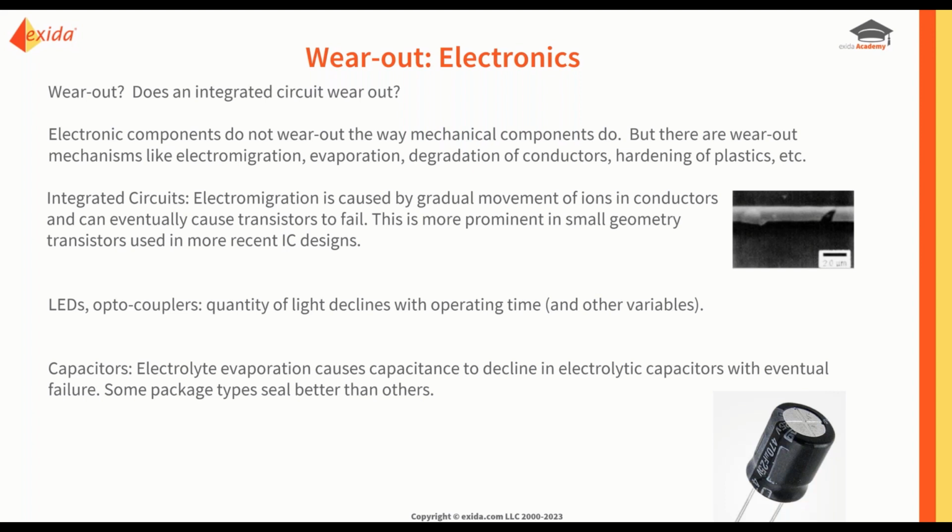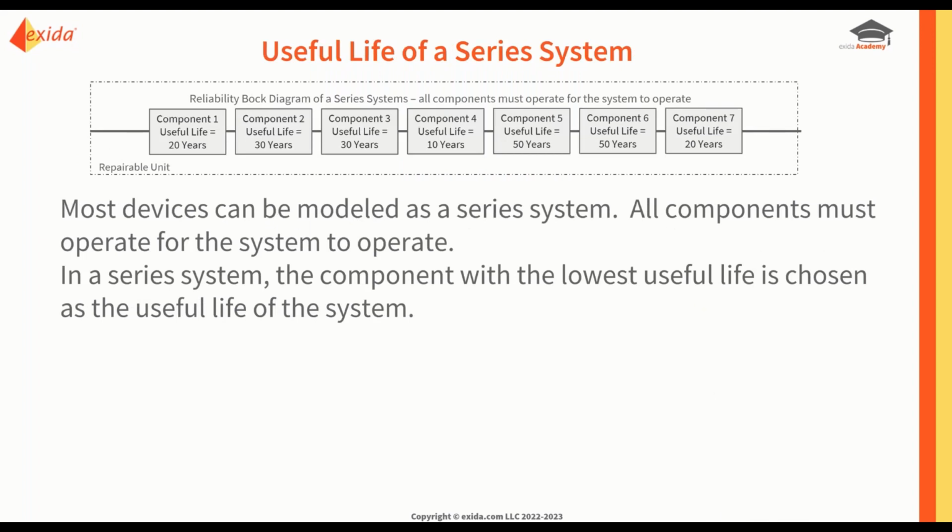Now, I will admit they're getting a lot better. The capacitor people are coming up with new chemistry and new designs that are so much better than what we had even 5 years ago. But you do have to watch out. You've got to understand the spec and the useful life of your components.